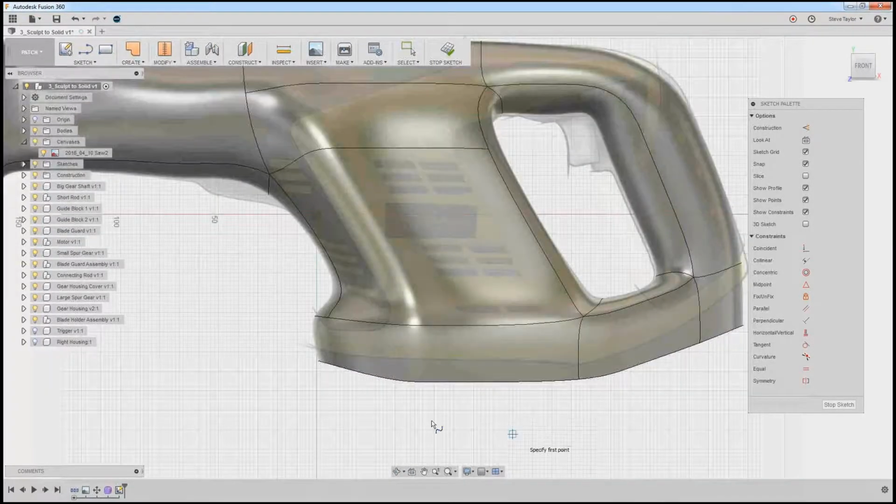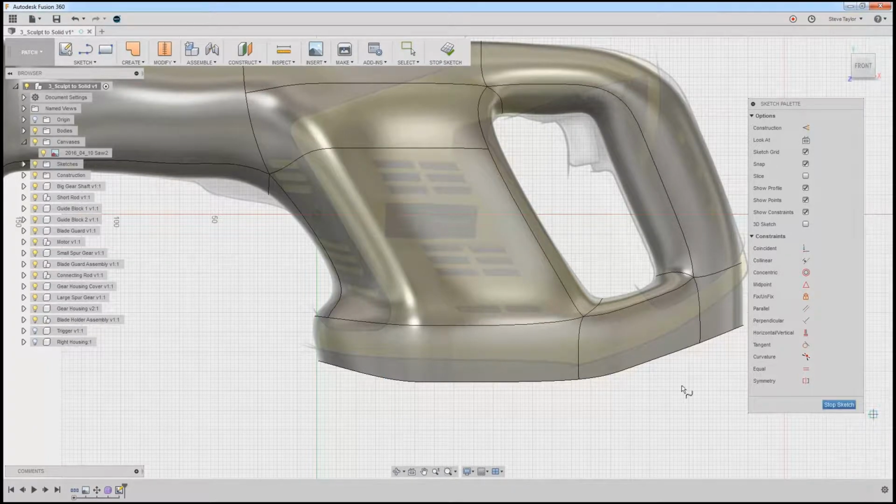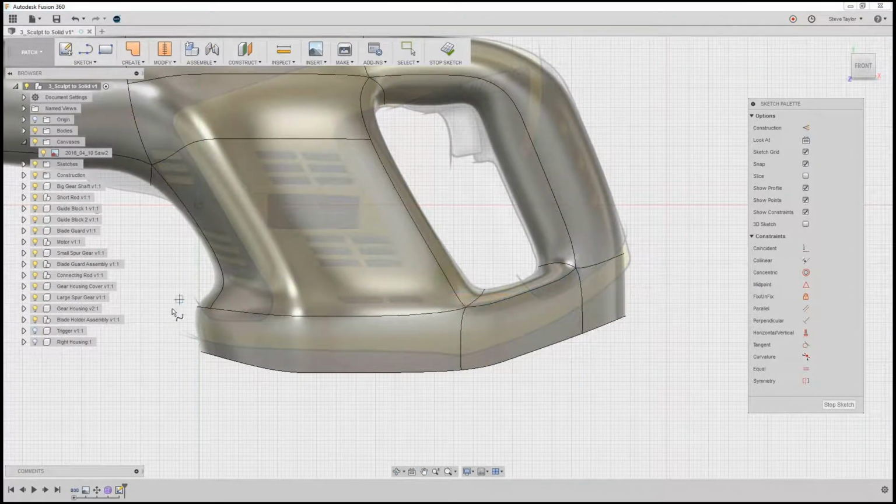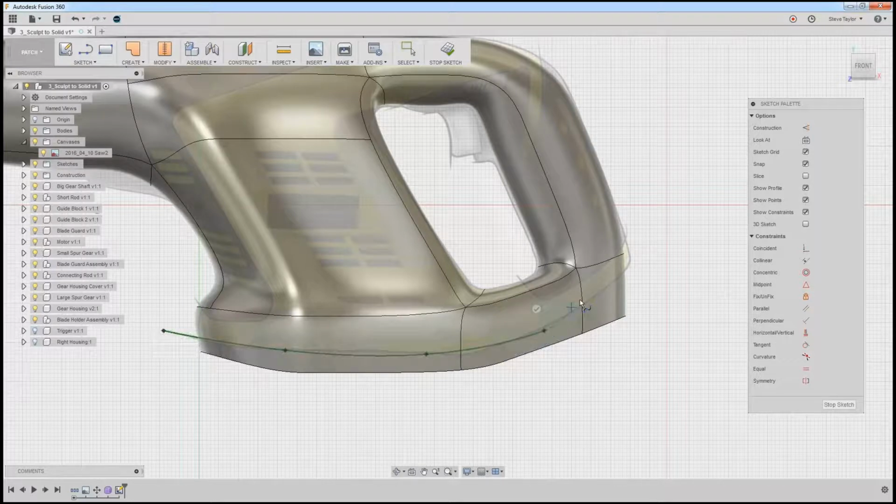Now what I'm going to do here, the first line of my body, I'm going to start out here somewhere. I'm going to draw a line that follows this around here, this little bit. So if I move that across and pan across, I don't want it to snap to any line, so I'm going to make sure when I start, I'm not being perfect. Again, just roughing this out. There. If I click the tick, it gives me this.